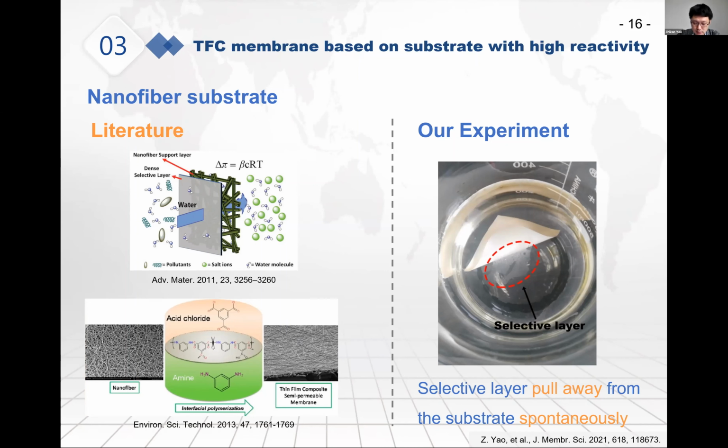However, something unexpected happened. We did not observe the high water flux in the FO test. Instead, we found a high salt flux because the selective layer would pull away from the substrate spontaneously. We must be missing some key points in the preparation of such a nanofiber substrate supported TFC membrane.